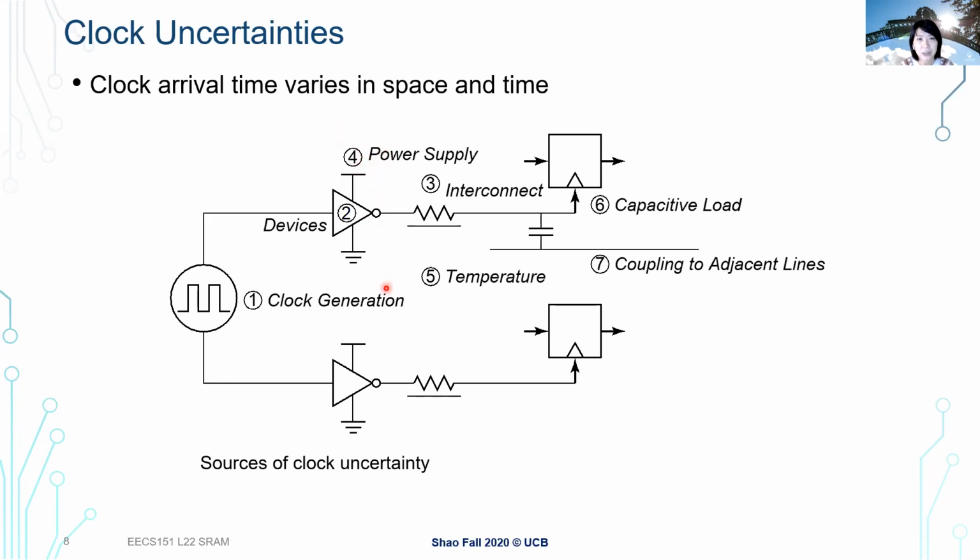If the power varies, that also affects the latency, right? So we talked about the voltage and how that affects the propagation delay, the latency, when we propagate a signal through the RC network. And finally, there's also different load. If we think about all the different considerations, it's really hard to say everything is perfect when we think about clock distribution.